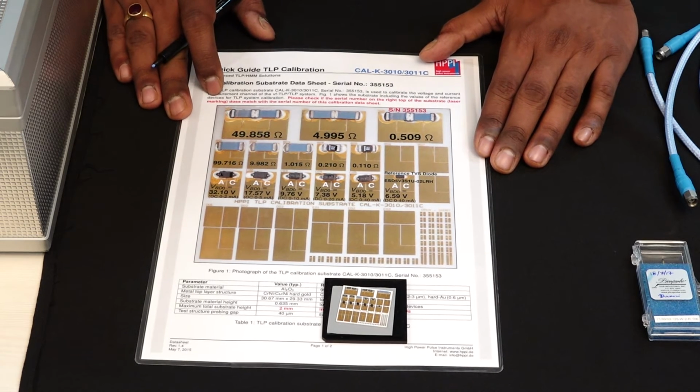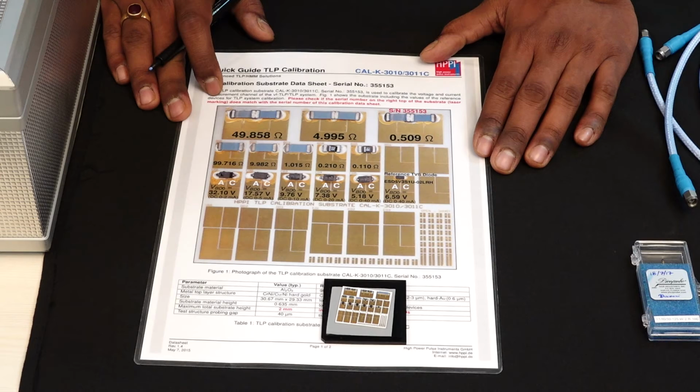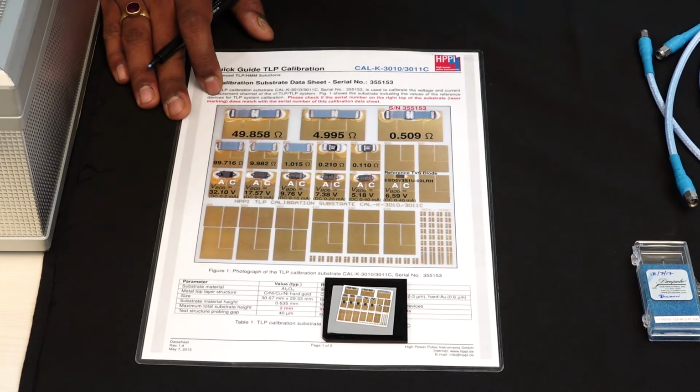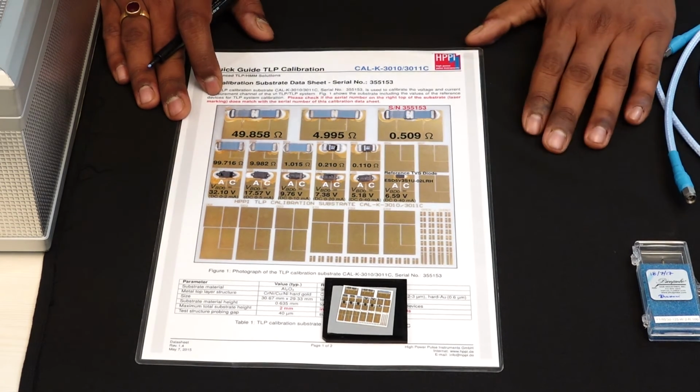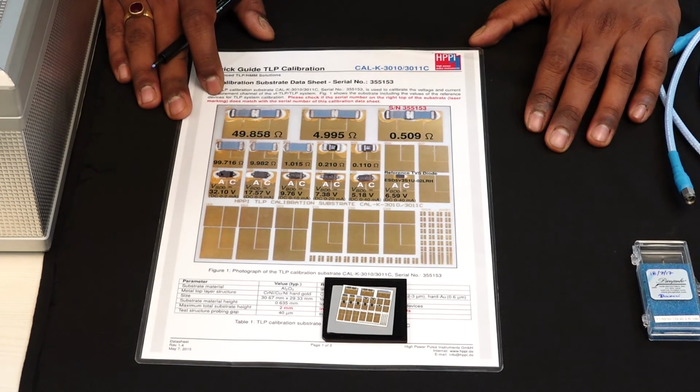Secondly, if a lot of time has passed and your setup has changed in terms of space, then it's always good practice to do the calibration all over again. But if you're going to do a couple of measurements one after the other, say in a 6-hour or 10-hour time frame, then it's okay to do the calibration once and use the calibration parameters throughout. But if there is a special movement of transmission lines, or any important factor has changed in your measurement, you will have to do the calibration all over again.